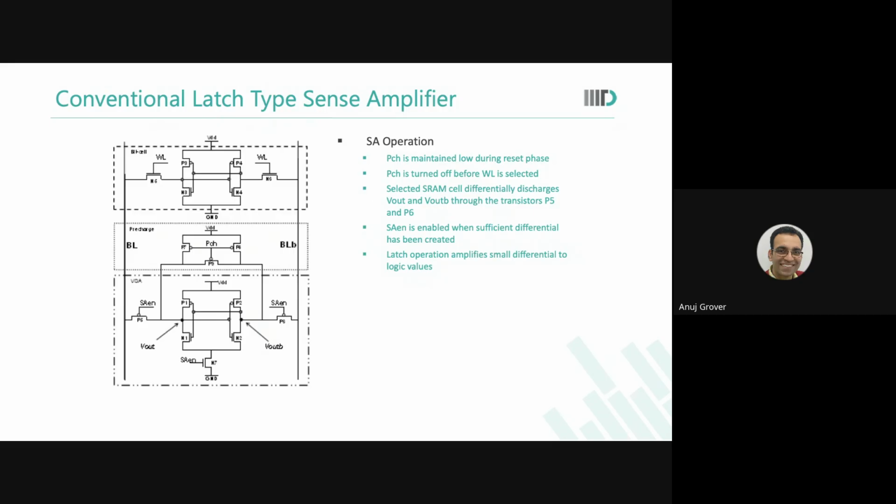Are you able to see this? Now, until now, what we've done is common centroid, guard ring. But in reality, you also need to take care of how the metals are drawn. Suppose for connecting these two lines, you use metal 2. Now, how will you connect metal A? You could say, okay, I will use metal 2 like this.